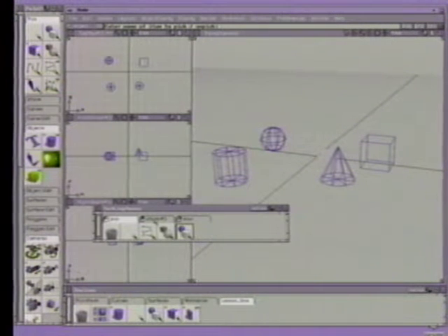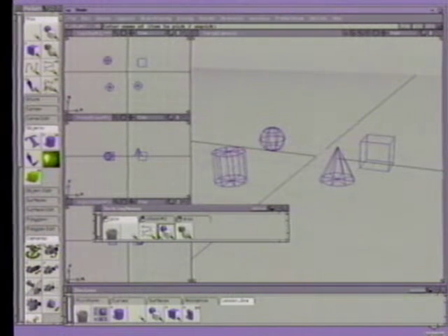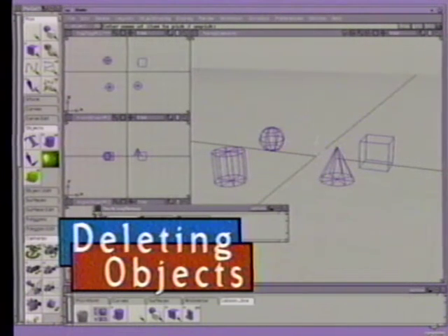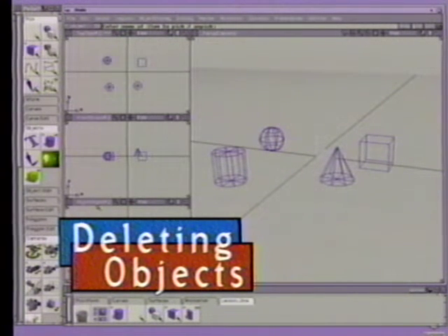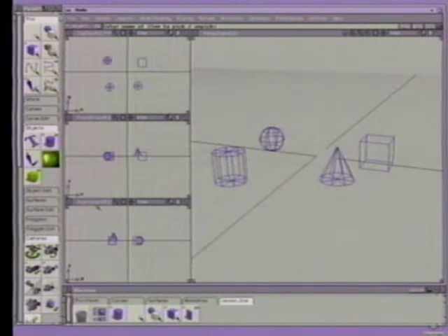This opens a special tool shelf that will allow you to set up your own marking menus using up to 8 tools. You can see that each of the tools that you saw in the marking menus has their icons in this special shelf. You can add to, delete, or reposition any of the tools on these shelves and therefore on the marking menus themselves. So far you've looked at how to place objects, but what if you want to get rid of some of them? Alias includes several delete functions to remove objects, lights, and windows from your workspace.